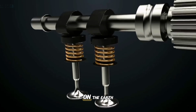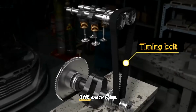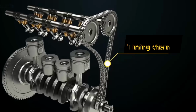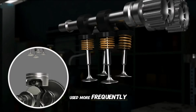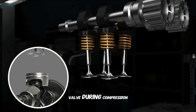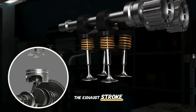The valve is driven by the camshaft. The camshaft converts rotational motion into linear motion. The camshaft is connected to the crankshaft by a timing belt. Timing chains are used more frequently. The intake valve opens during the intake stroke, and stays closed during compression and power. The exhaust valve opens during the exhaust stroke.